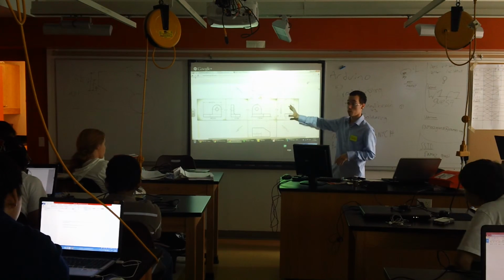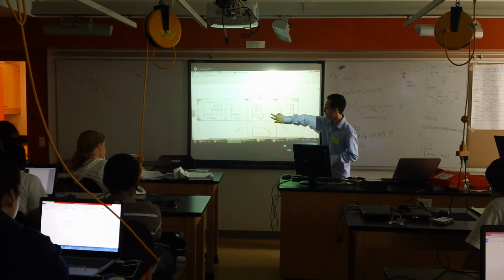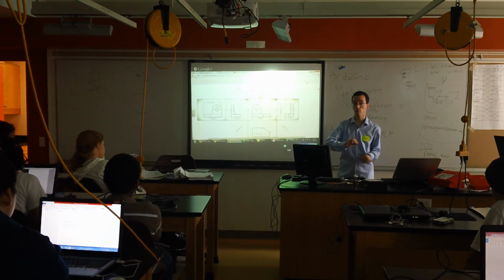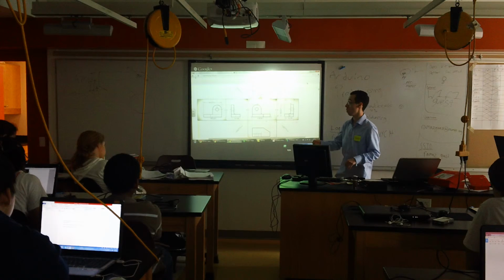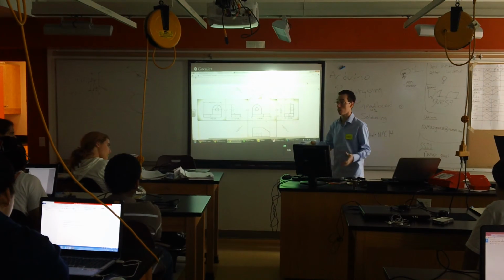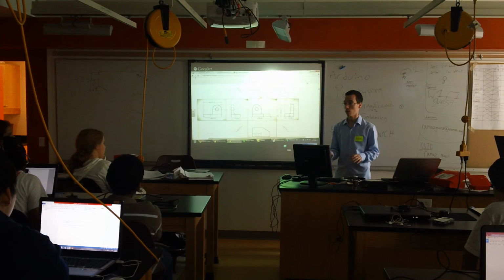Project different views, dimension them all, but don't put any excess information in here. If I dimension this and say this is this tall, I don't need to do it on this view too. The machinist needs exactly enough information to make your part and no more, because then they'll start to wonder, why did they specify here? Are those 2 different views? Am I not looking at the same thing? It gets confusing and frightening, and machinists are very skittish and we don't want to scare them away.